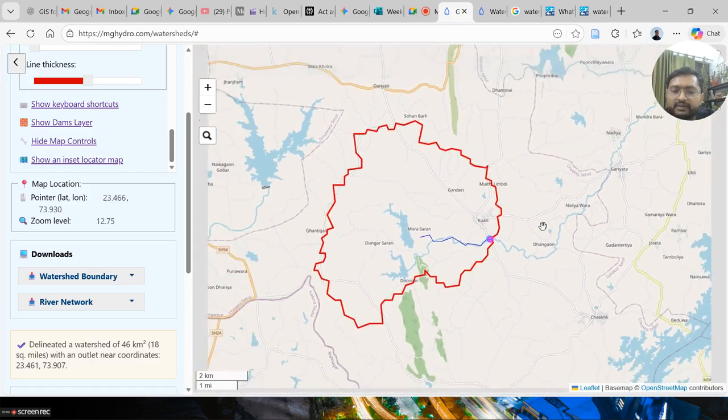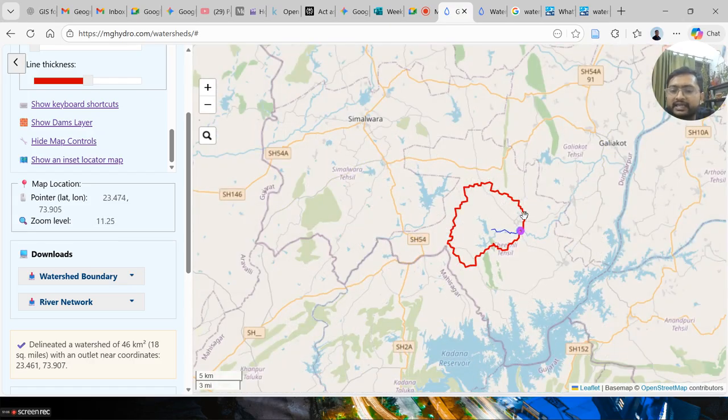So that's information I will get to know, and based on that I can take certain steps, and I can calculate the amount of water. If worst case rainfall happens in this area, then how much volume of water will come to the location, and based on that I can design my hydraulic structures, that what should be the opening and how much area I should keep so that water can pass properly.